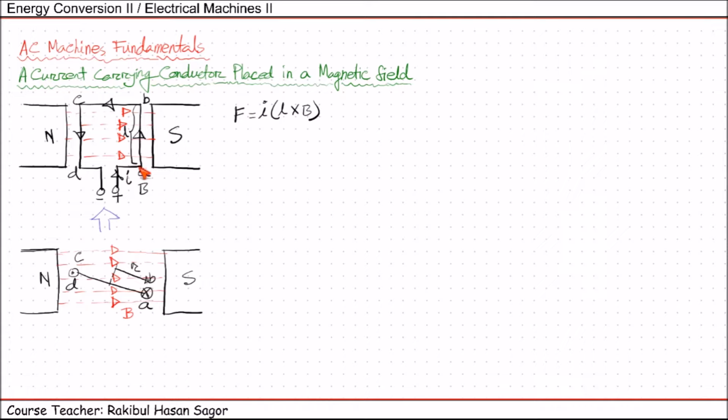So if the current is flowing from A to B, this length is the magnitude and the direction will be from A to B. In this way, by seeing the direction of current flowing, we can figure out the direction of the length L. Hence, the torque on each segment can be represented by tau, which is equal to force applied, that means linear force applied, multiplied with r, I mean from center to the distance of the conducting wire that is rotating, sine theta.